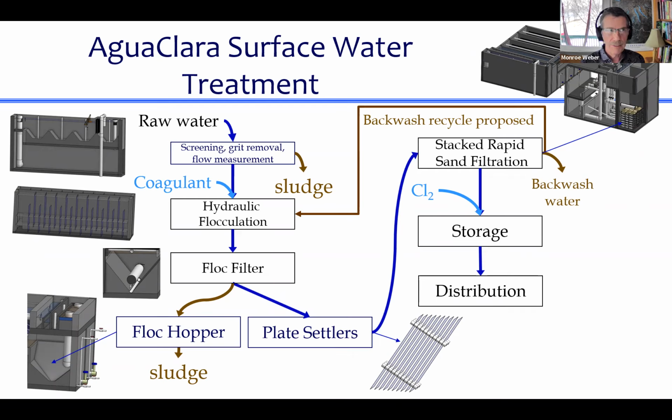which we're calling a floc filter. In the literature, it would be referred to as a floc blanket. And I have rebelled against that term ever since I first heard it, because it is not cozy. You cannot use it to wrap yourself up and keep warm. And it doesn't look like a blanket. And so it's not clear why the term blanket was added to that. And so now that we, as of about a year ago, have a much better idea of what the physics is of what's going on inside that system, we're going to call it a floc filter. That's in the bottom of this sedimentation tank that we're going to be studying.